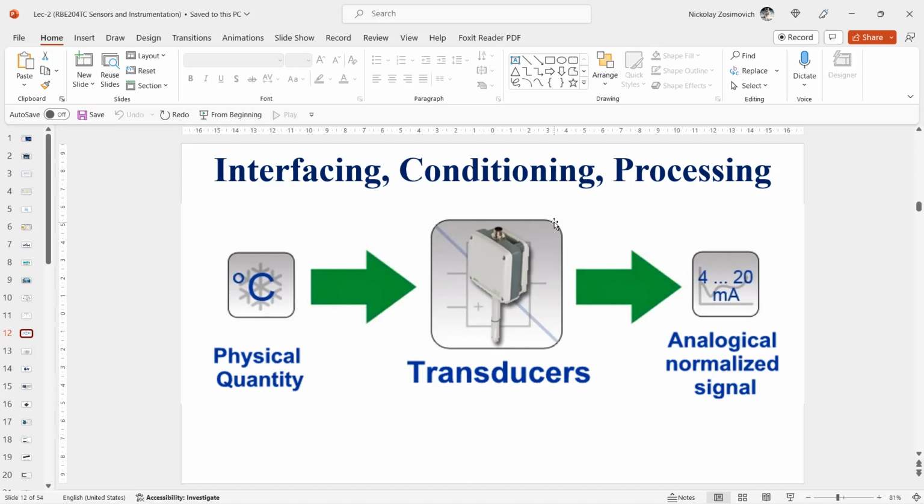Alternatively, sensors can also be designed in such a fashion that their primary output is already in the digital domain. It may be an incremental encoder or, especially, absolute optical encoders, which give the output in digital steps or bits.